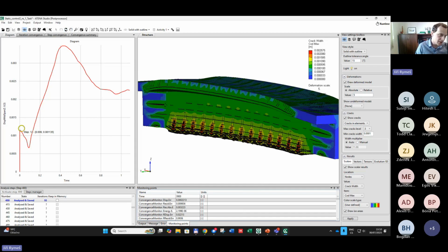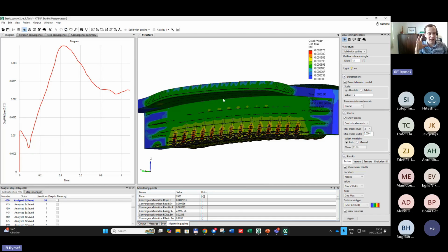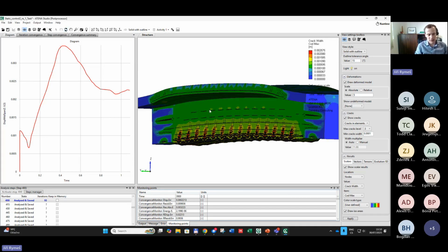I can see how the deformation of the sample evolved during the loading. Typically a change in the trend indicates some crack opening. So basically the model wants to bend some way due to the thermal stresses. However, at a certain point, these thermal stresses exceed the strength of the material, the crack deforms, and it can change the trend of the behavior.